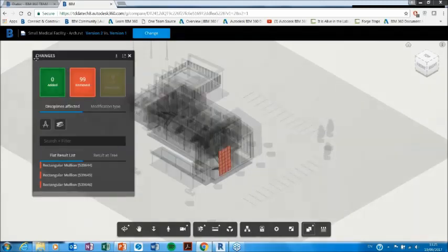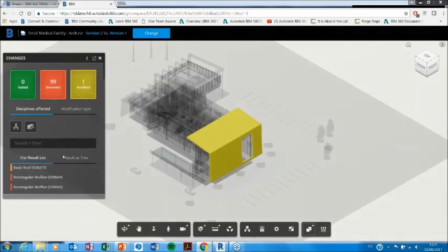And that comes up. You can color code it per object, or you can actually filter it to, was it your electrical engineer or your plumber, or was it your glazing specialist or consultant who made the change. You can isolate them there with these different filter options here. And it actually tells you how many objects were removed, which you can set up in Revit if you think it's relevant to use. And then again, you can add comments to that as well.